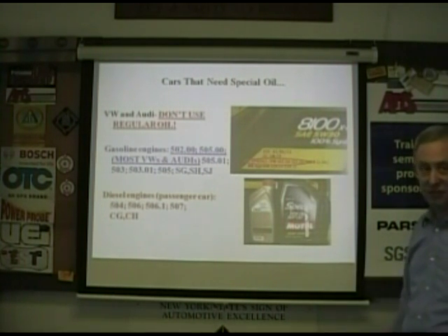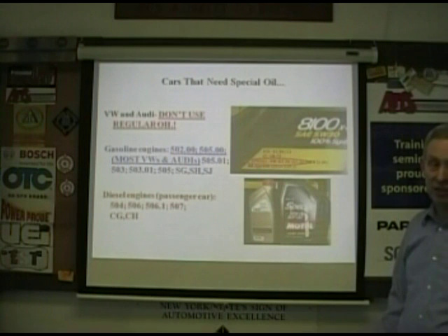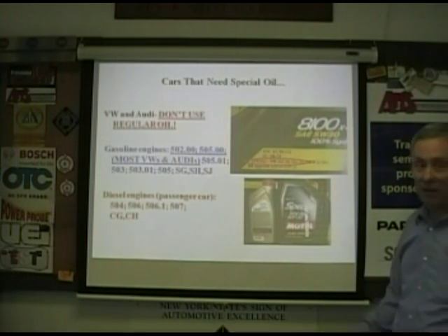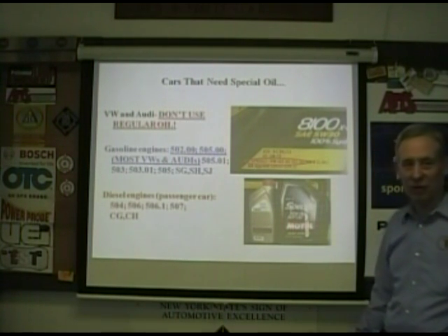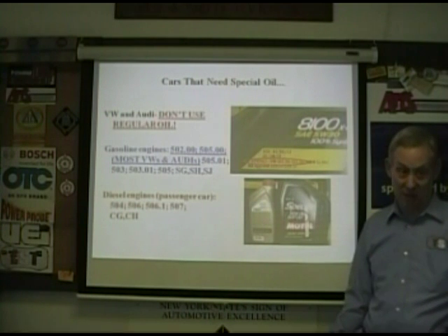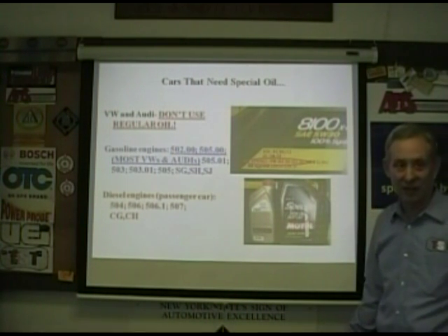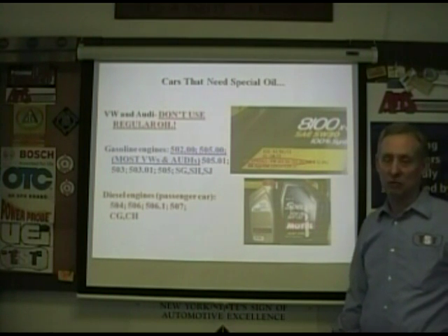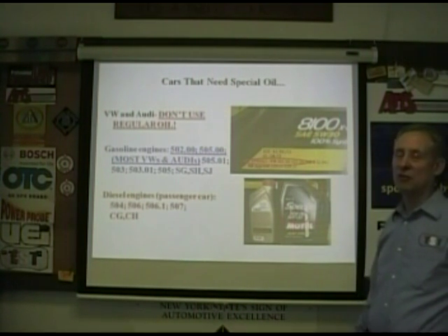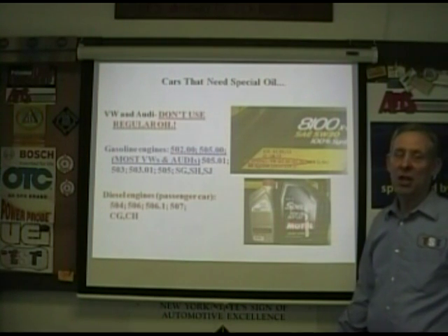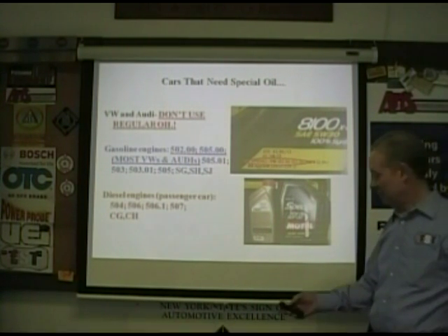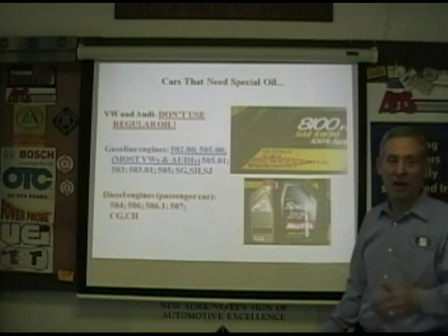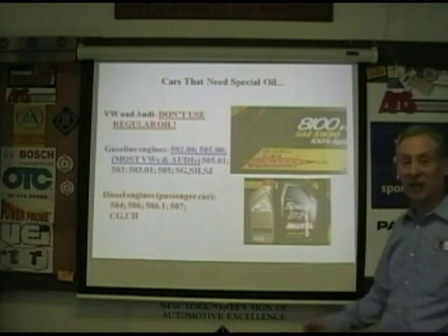We had a case in this VW dealer I'm now in, when I was there only a few weeks, where the car had 90,000 miles, and it had been going to a place that was using regular petroleum oil, which did not meet the VW spec, for 40,000 miles. They got away with it, they thought, for 40,000 miles. The car came in with an unusual symptom, which was losing the oil pressure light at revs, not at idle. And what was happening was so many chips of aluminum and other things were in the engine that it was plugging the screen, but it was acting like a sock. As the engine revved up, it was sucking the stuff up and blocking oil flow, and as the revs went down, it was getting lubrication, barely enough.